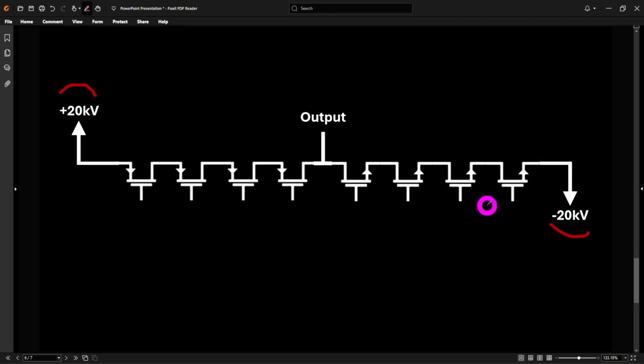Now generally, it doesn't really matter whether you use a solid state transistor or use a vacuum tube, everything is going to have some level of breakdown that you have to overcome. Generally, without getting into semiconductor physics, solid-state devices, their breakdown gets worse as transistors get faster. It has to do with the fact that you're shrinking things down, the dimensions are smaller, and naturally breakdown gets worse. Other things change too. But in general, it's very, very difficult to build transistors that have tens of thousands of volts of breakdown across them. So we have to make the problem a little bit simpler.